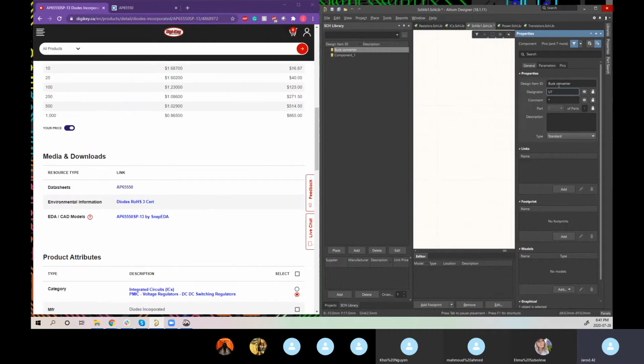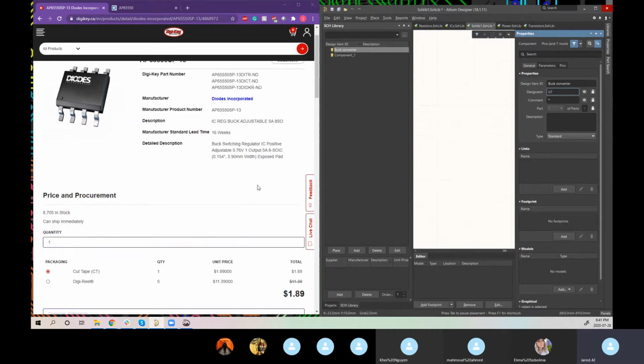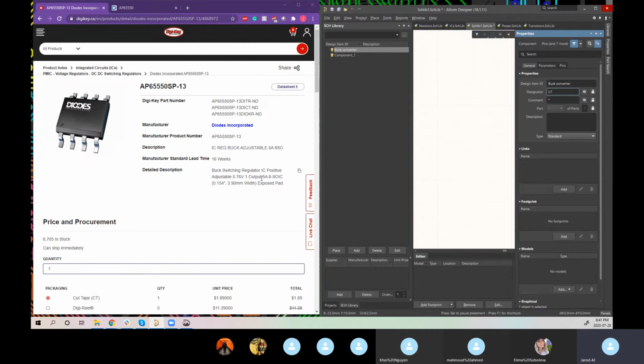There's a couple ways you can do your commenting and description. Best thing to do for your description is when you find your part in DigiKey, you just straight copy paste the description it has. So that'll be your description. And a good kind of system that we run is you take your manufacturing part number and you make that your comment. The manufacturing part number is your comment.